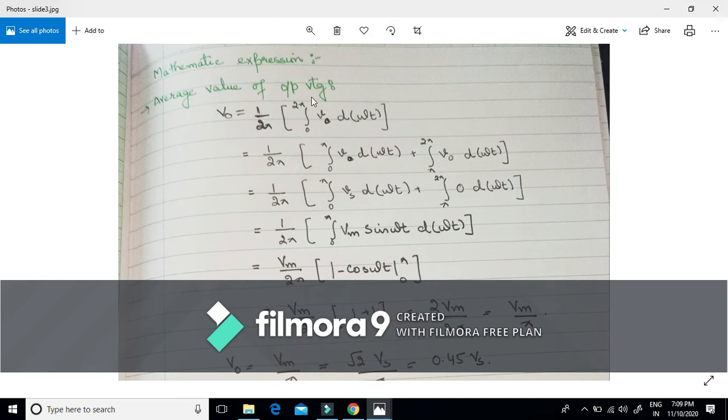Since we know that the average value of output voltage will be equal to 1 by 2 pi, integral from 0 to 2 pi, V output d omega t. And since we know that from 0 to pi our diode is conducting, and from pi to 2 pi our diode is not conducting, I have divided it into two parts: 0 to pi, V output d omega t, plus pi to 2 pi, V naught d omega t.